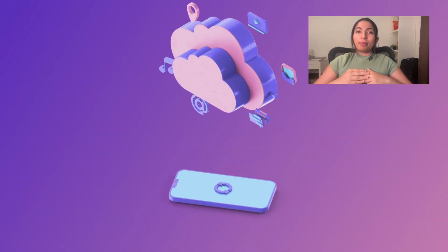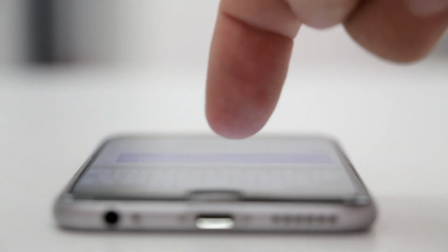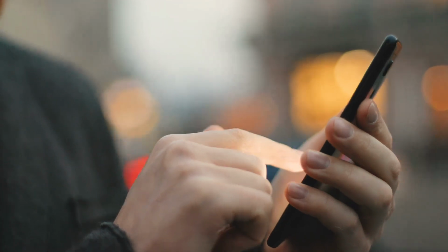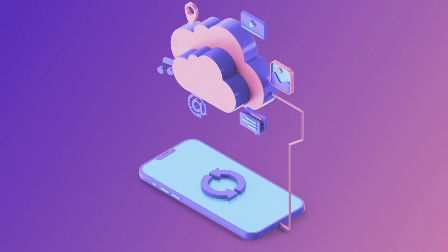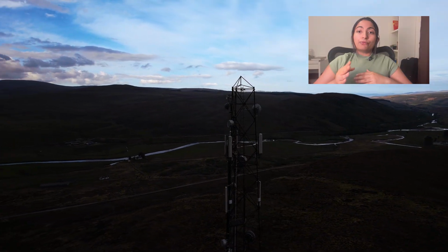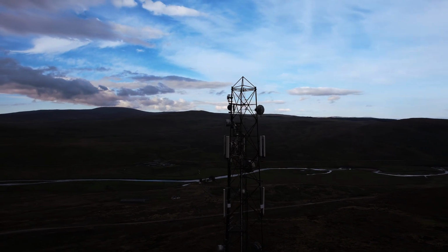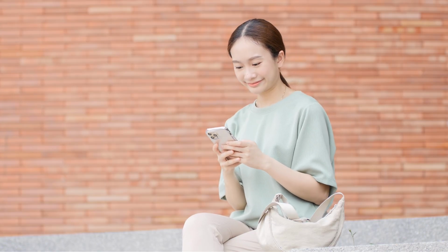Every time you turn on your mobile phone, it has no idea where it is. No cell, no signal, and no clue which frequency to listen to. Somewhere out in the 5G FR1 band, from 410 MHz to around 7.125 GHz of spectrum, one specific channel is being broadcast by the gNodeB, and your phone has to find it blindly. There is no GPS assist, no hint, just raw searching hundreds of thousands of channels wide. And it does so in a fraction of a second every single time you power on your mobile device.